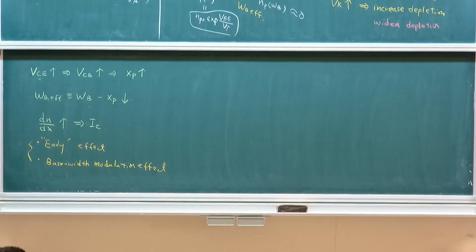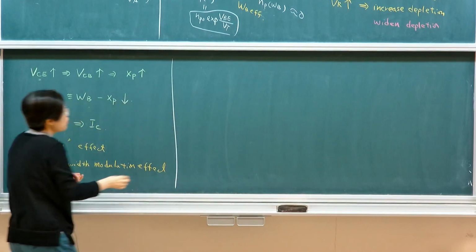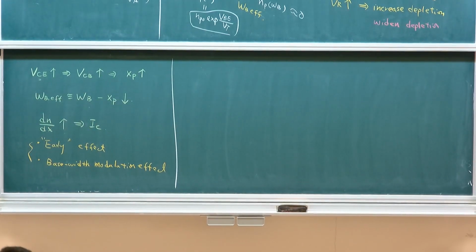Okay? So the next thing I want to talk about is, okay, we already have our model. What is the implication? The most significant implication, other than projecting your DC current, where you have to do a correction, meaning maybe a 10%, 20% correction in the output current level. So I have the correction term, right? 1 plus VC over VA. This is not the key impact on the overall behavior. The key impact is actually at the output resistance.